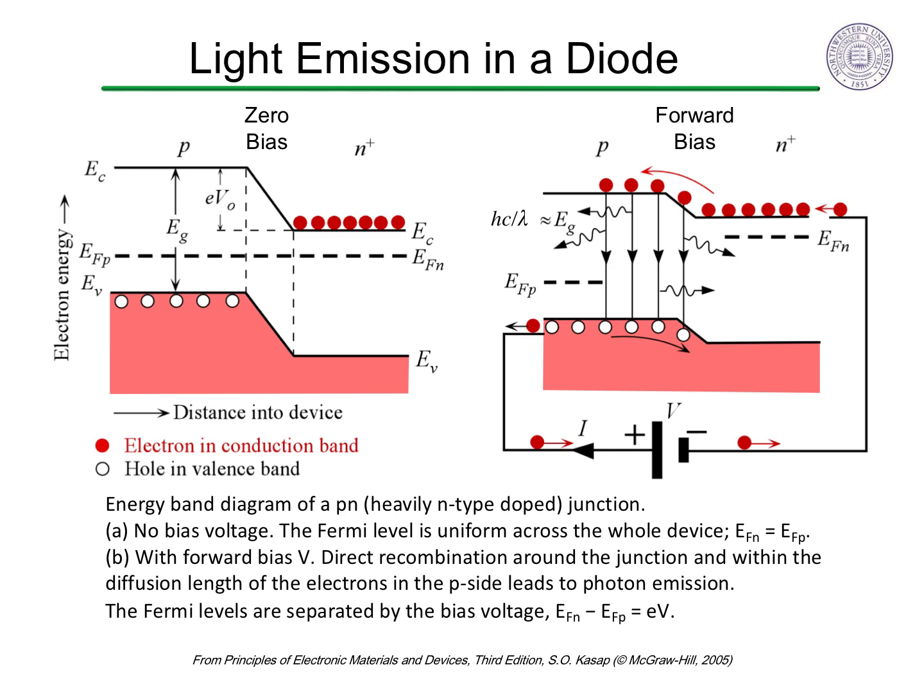Forward bias adds negative potential to the N-type side, pushing electrons into the junction, and positive potential on the P-type side, pushing holes into the junction. When there is a forward bias, the built-in voltage barrier is reduced, allowing the current to flow into the depletion region, which we call current injection. Injection of electrons and holes brings them close enough to recombine and produce light, called photoemission, with an energy approximately equal to the band gap. They can recombine in the depletion region of the junction, or if they don't recombine before they reach the other side, they become excess minority carriers and recombine later.